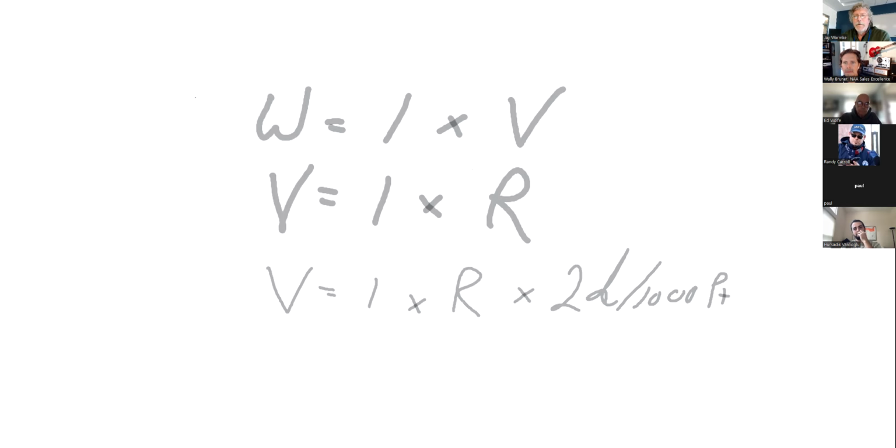Okay, I know VOC. I don't have to know anything else. The other thing you have to remember is that when you're doing temperature string calculations, what's the minimum and the maximum of the string, with the minimum number of panels in a string, you do that on the hottest day ever, and there's a temperature adjustment based on how it's mounted.